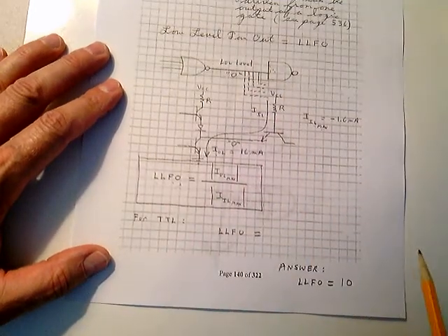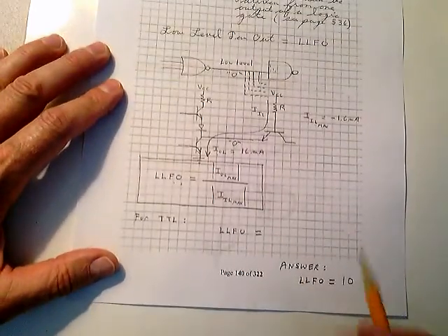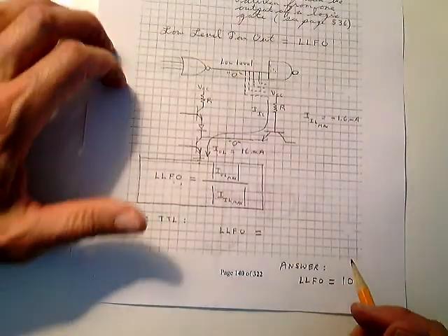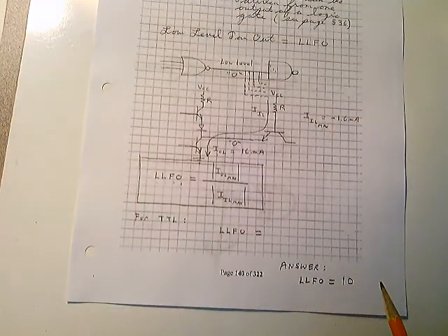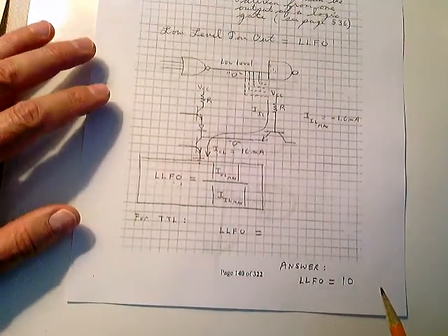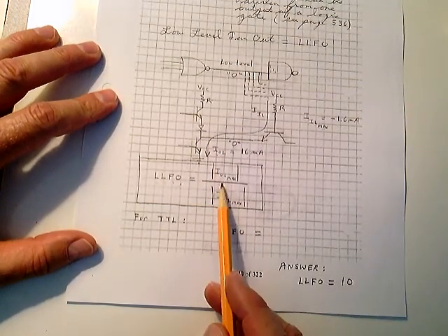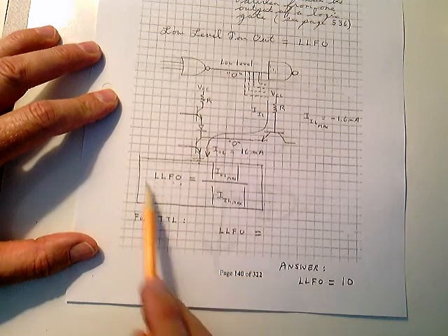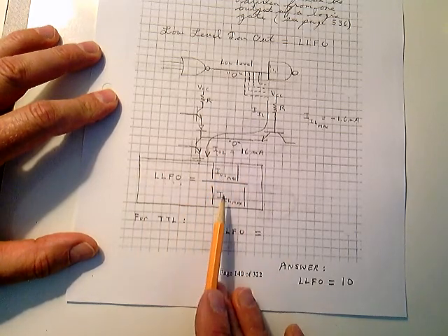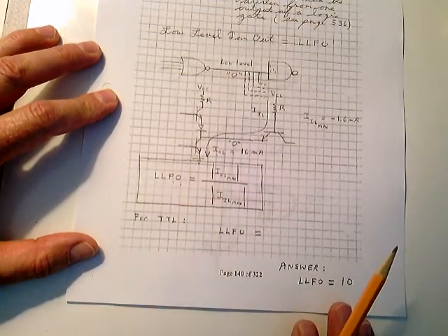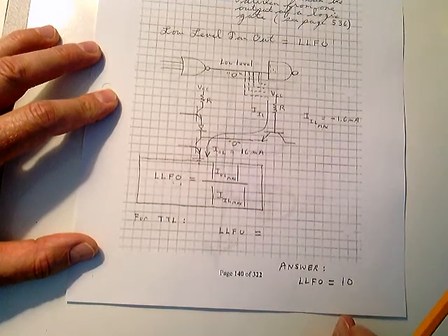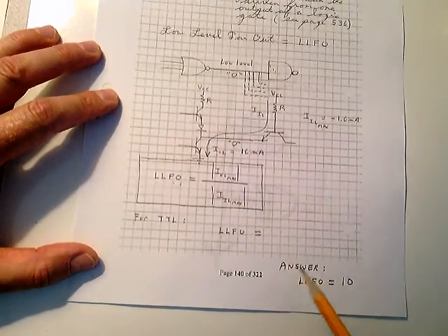And then I have some people that say, you know what, I took it 11 places. I took it 12 places. I took it 13 places and it worked. Well, yeah, maybe it did, but there's a trade-off there. The manufacturer says, according to this equation, and this equation's good for every logic family, just the specs, the numbers change here. They're saying they'll guarantee a fan out of 10. It may work 11, it may work 12.